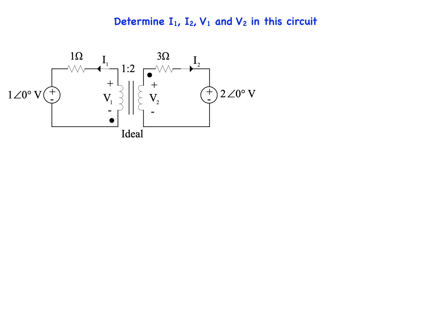You will have noticed that I have assumed a current direction flow. If this was a DC circuit, this assumed direction is obvious. However, when dealing with AC, it is a little less obvious because, of course, the current is reversing every half cycle. In AC circuits, current direction is defined as the direction that current is flowing in the positive half cycle. That produces a voltage drop, positive to negative, in the resistive elements of the circuit.